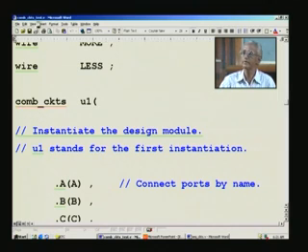So, this is different from the test bench. We had declared a module called combination circuits underscore test, whereas we are calling the actual design only here, and this you can call any number of times. It is similar to, suppose you have a circuit diagram, let us say we have TTL gates, say 74LS00, you have used, there are 10 numbers on a board, and how do you identify? You identify them as U1, U2, U3 and so on, that is the nomenclature you adopt, and very same thing has been adopted here also. You can just call this once and treat this as one particular package, one IC, like this you can call any number of times, right, and any other module you can call here.